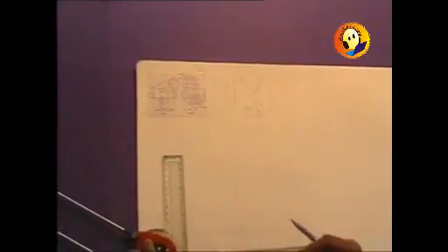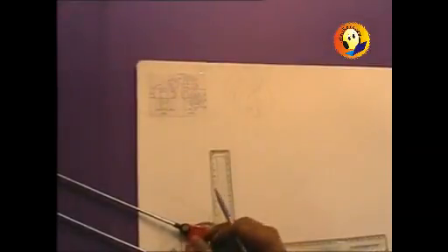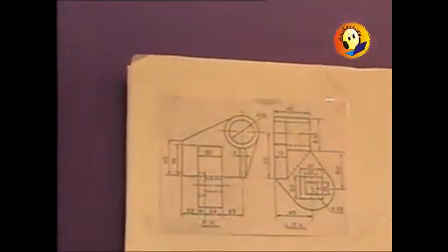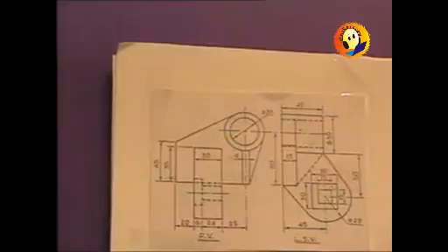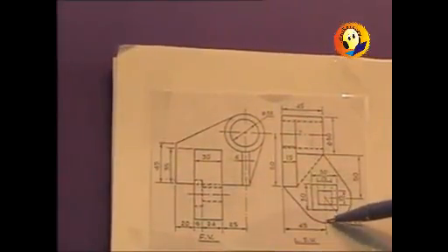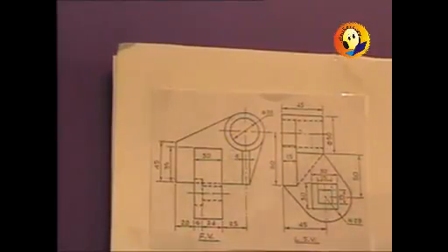So these two lines are drawn. And now let us go for marking the different blocks. I have already calculated that the total height of the object, if we again look at the given figure, then we can very well imagine what is going to be the total height of that particular object. We can see that the height is 50 plus 50, and then below this it is 28. So height can be considered as 128.